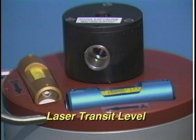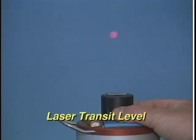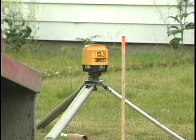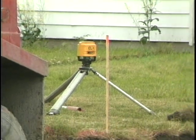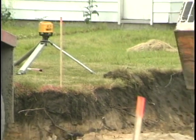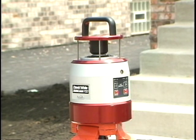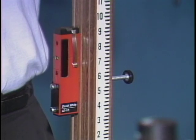To monitor grade and depth of the excavation, set up a laser transit level as an elevation reference point. Set up the level on one side of the lot out of the way of the workers. Level the laser and turn it on. The laser will then spin while emitting a strong laser light beam.